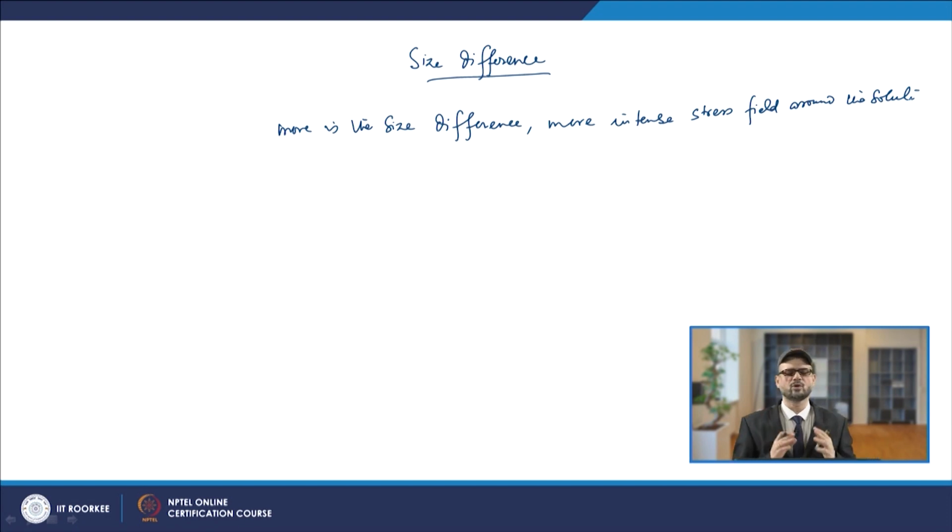The more the size difference between the solute and the solvent atoms, the more intense the stress field around the solute, and once they interact, the more stress is required to move the dislocation. That is a stronger interaction, so more stress is required to move the dislocation.